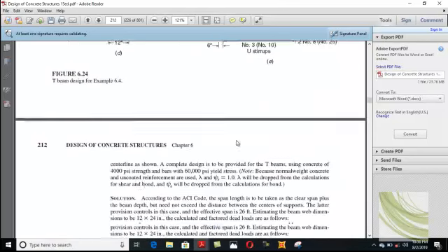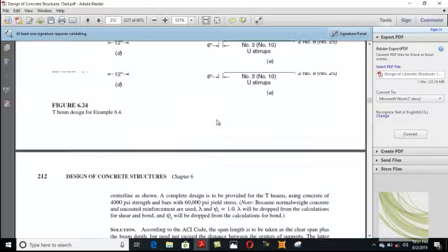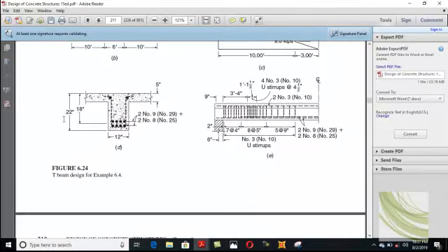Where it is, okay, 24 inches. So then we will revise our calculation. We will revise our beam width for that value which we get from shear criteria. Now 24 is more than 22 inches, so therefore we don't need to revise our calculation. Okay? And you should remember that 18 inches and 22 inches.